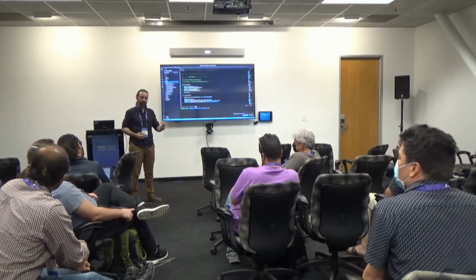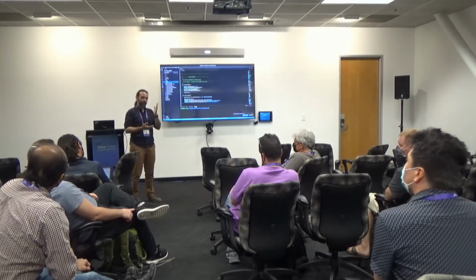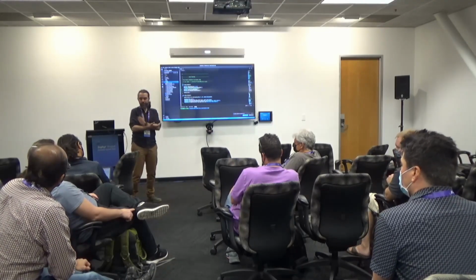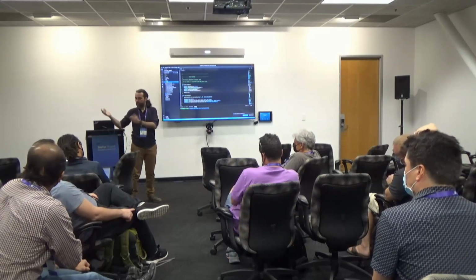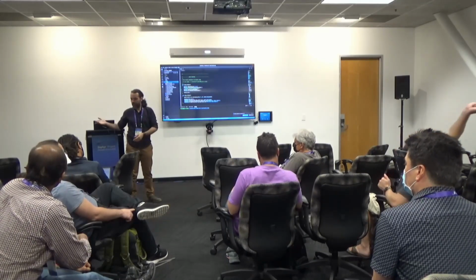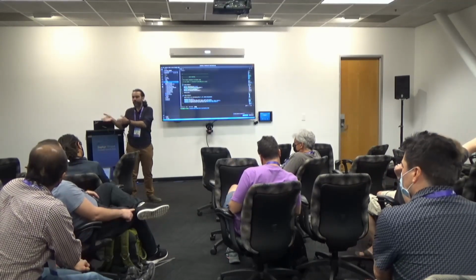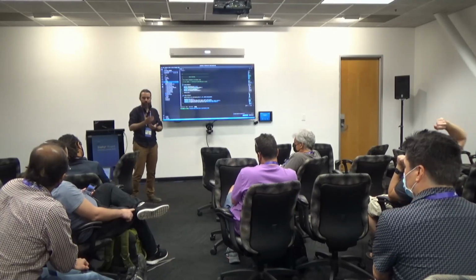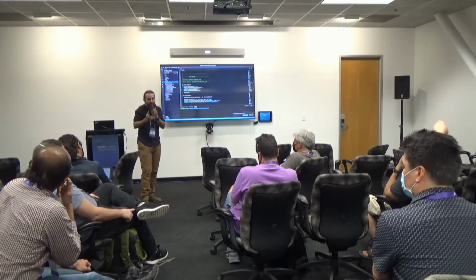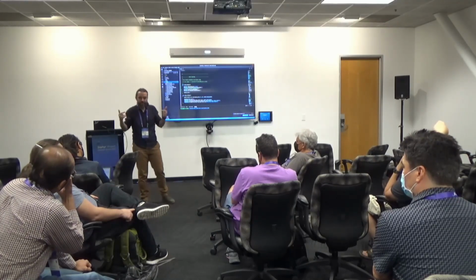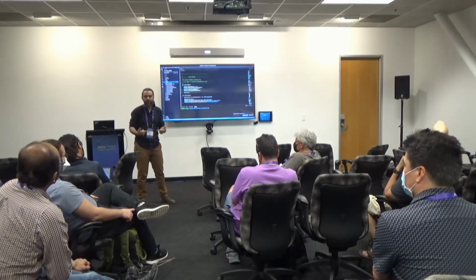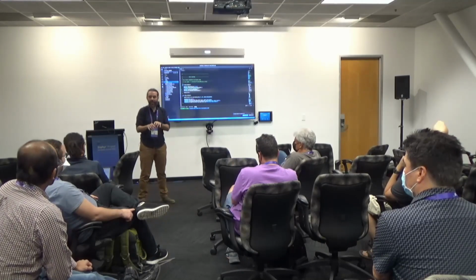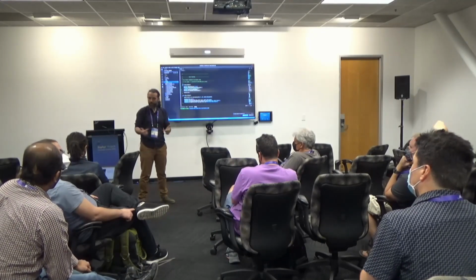You're telling one peripheral that its trigger comes from this register, and telling the other peripheral to write its trigger to this register, and they're triggering at the same time. It doesn't go through the MCU. You set it up via software, but it is a peripheral-to-peripheral setup.